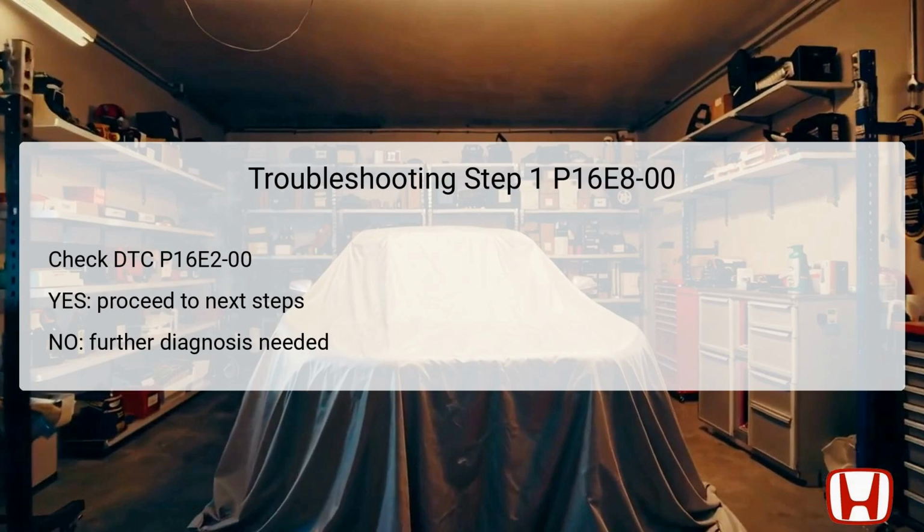The first step in troubleshooting the P16E8-00 code involves checking for another DTC, specifically P16E2-00. This code is related and might indicate another underlying issue. If P16E2-00 is present, it signifies a separate malfunction that must be addressed before moving on.